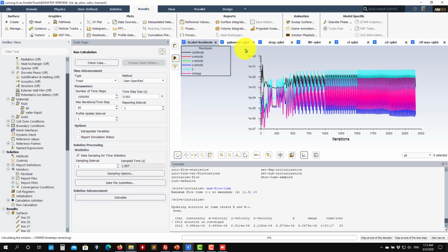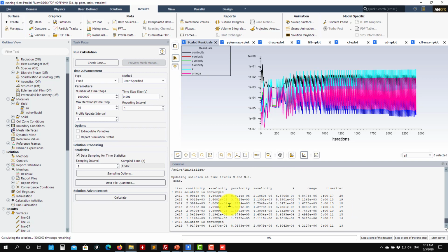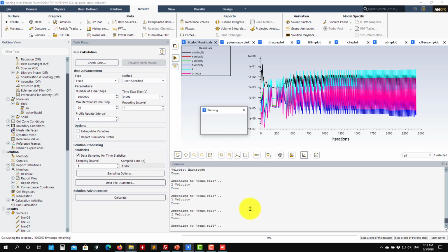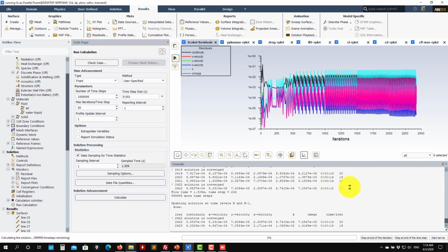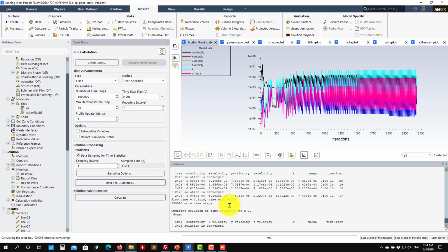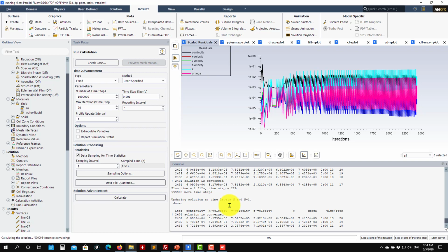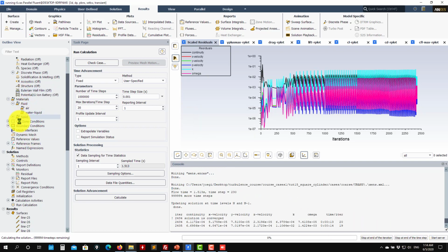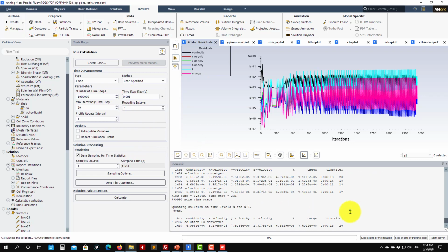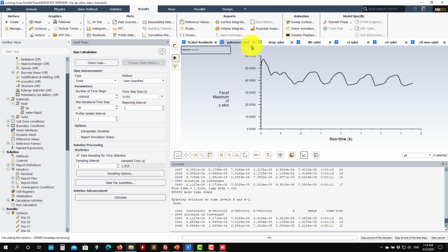Okay, so by reducing the time step, as you look here, your iterative convergence... At the beginning every change will take longer, but see that it is going faster. So maybe it would be a good idea also to increase the saving frequency of the files, because now we're saving every 0.005. What you can do is go back to the activities and just multiply by 50. I won't do it, but you got the idea. But see that it's going faster.